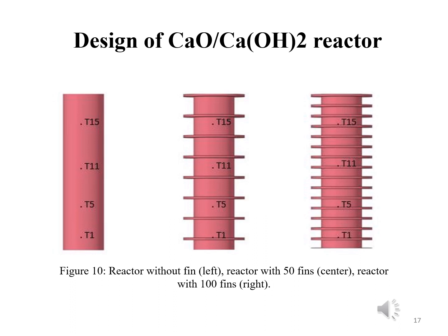Second, with 50 fins, was done by Harsh Nakum, and third, with 100 fins, was made and done by Shivam Parmar. The reaction which was made into focus was the charging, or say hydration, process, in which calcium oxide is there on the reactor bed and high temperature steam strikes on it from the top, which results in the formation of calcium hydroxide, and heat is dissipated in the atmosphere.